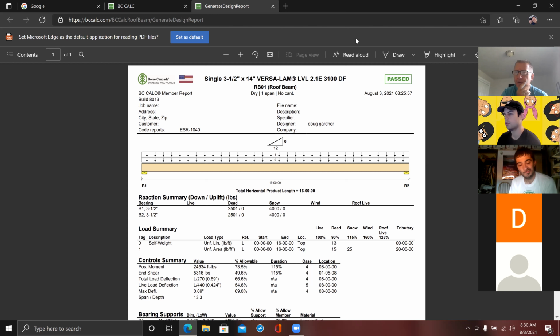Yeah, right. And I will tell you in a residential sense, that's because beams are always going to deflect. They deflect under their own weight, if that makes sense. So they're going to deflect some. And the issue is just, will they bounce up and down? If you put it in and it was bent and it just stayed bent, then you could build around that and it really wouldn't hurt much. But the problem is when it snows, does it go down and then go back up and go down and go back up? And you're right, that's why I said 1 inch is really kind of arbitrary.